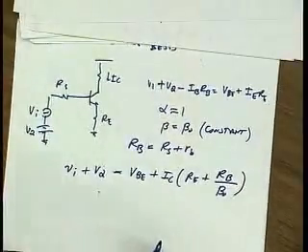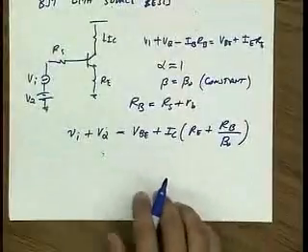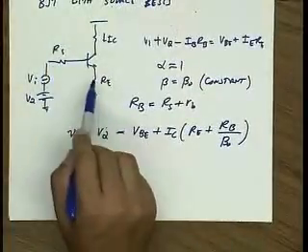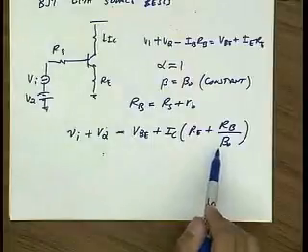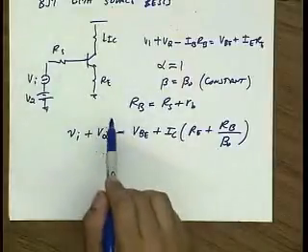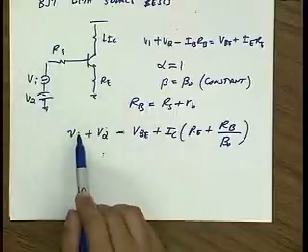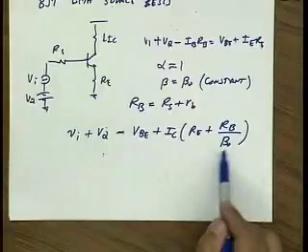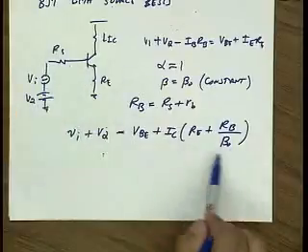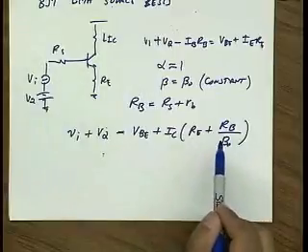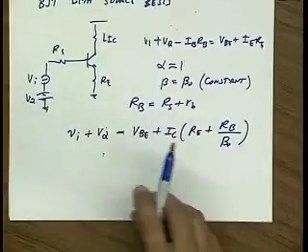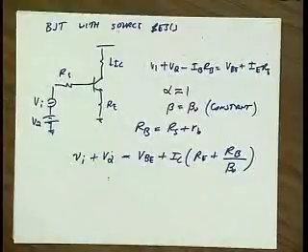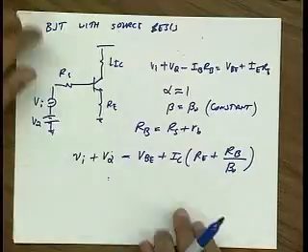In other words, as you guys know from your basic electronics courses, I can take a resistance and move it over to the emitter by just scaling it by beta, because the collector current and the base current are always related by beta. So therefore the emitter current is also related to the base current. So in other words, I can absorb any kind of source resistance and treat it as a feedback resistance in the emitter. Okay? Questions? All right, well, what about an emitter follower?